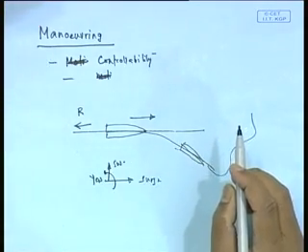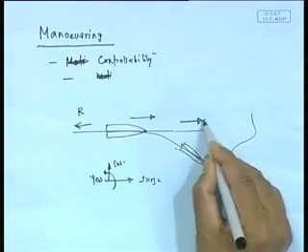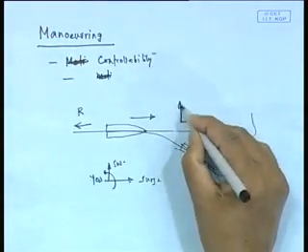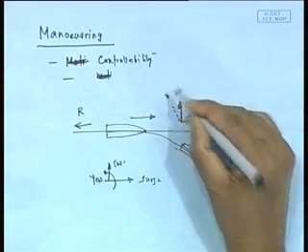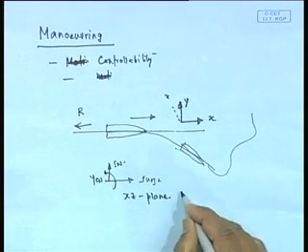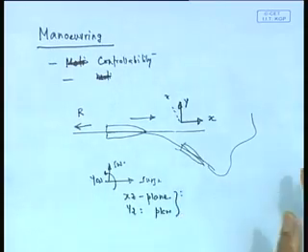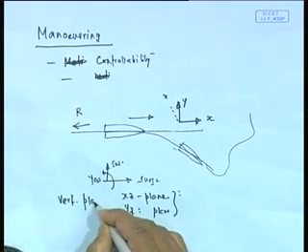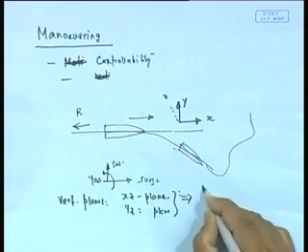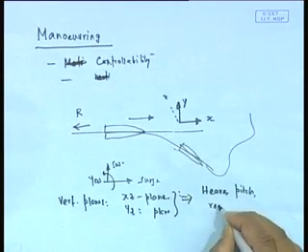Of the 6 modes of motion, if I call this the x axis, this the y axis, and the vertical the z axis, in the xz plane and yz plane, the central plane and this plane, the vertical planes, it gave rise to the motions heave, pitch, roll.